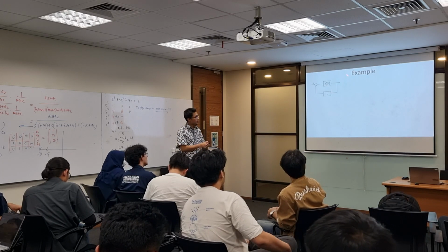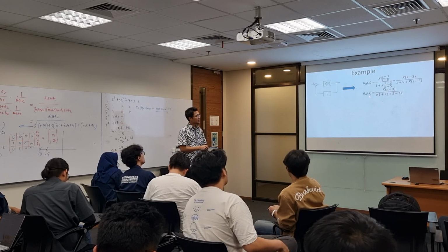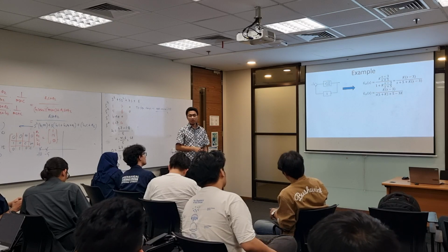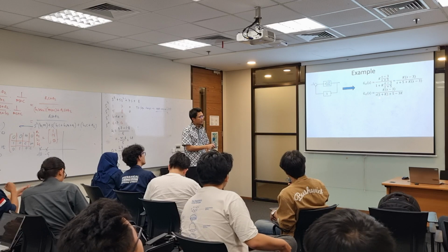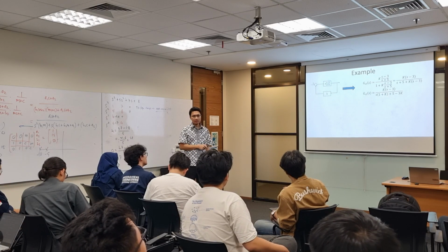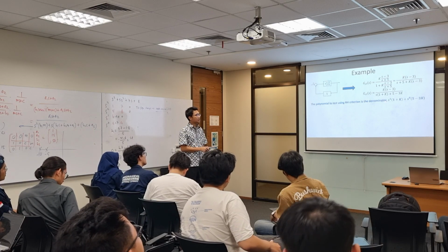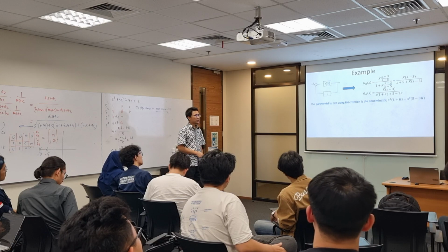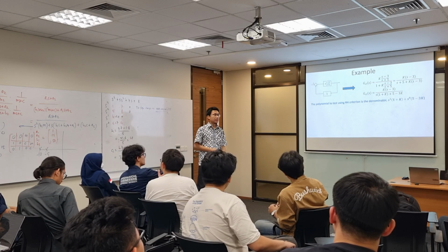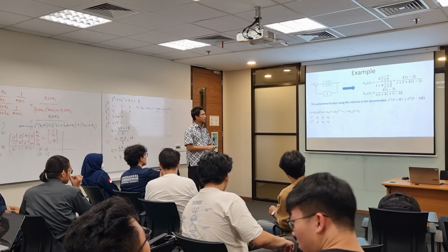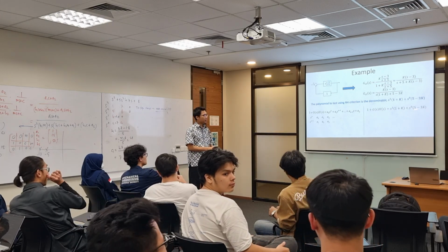Another example, which is the first example that we have. This is the closed loop transfer function. If I want to know the range of k which makes the system stable, then I will check the denominator, not the numerator. So this is the polynomial, because I want to know what k can make the system stable. This is the reference, and that's my polynomial.